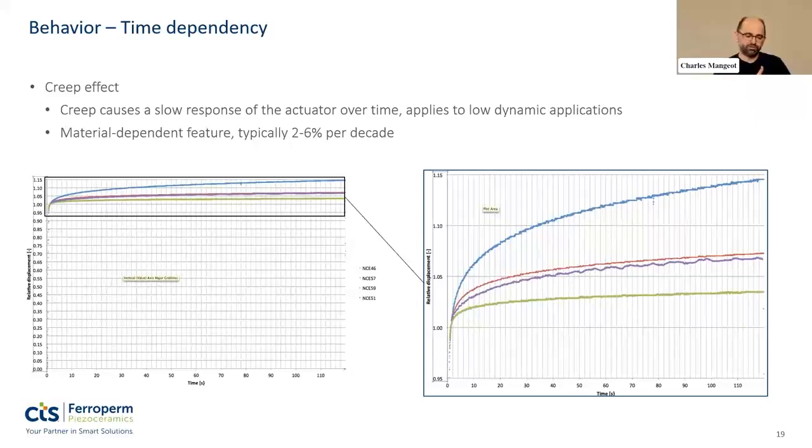And the same goes if you go very fast. So if you have very fast hysteresis loops, then a part of the material will not have time to react. So the curve will tend to look more round. And if you do it really, really fast, then you might also have some dynamic effect that comes into play, so that the material maybe doesn't have time physically to move in the way that you expect it to. So basically the curve gets more round as you increase the frequency.